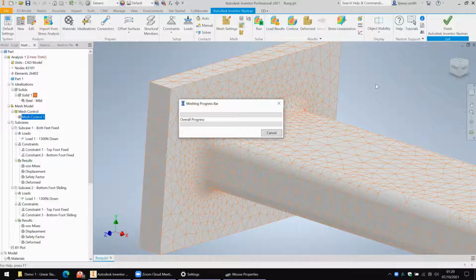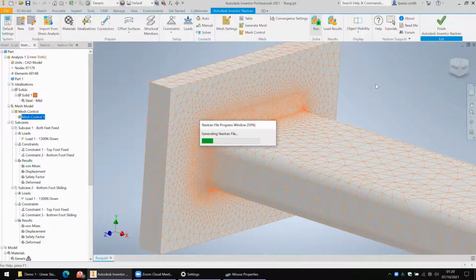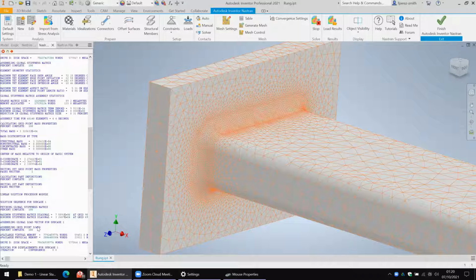These habits that analysts tend to take on, such as starting off with a rough mesh and gradually refining it in areas of interest, what kinds of mesh to use, what's the most appropriate elements. All of these are, I suppose you could say, software agnostic, whether you're using NASTRAN or another company's analysis software. These tend to be habits that you learn being an analyst, and something that we cover during training. So let's have a look at our von Mises stress again.